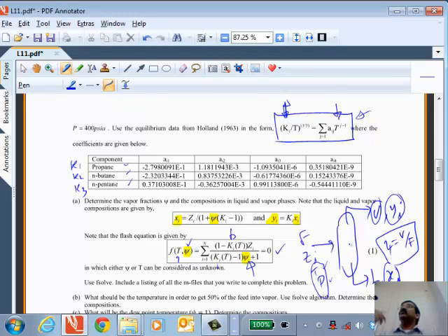So at dew point, what do you think will be the vapor fraction? Approaching 1, right? Because all of it is vapor, only one drop forms as a dew. Okay? So the vapor fraction is 1. So by putting vapor fraction equal to 1 in here, I'll be able to calculate the dew point. So the same formalism, same set of equations will allow me to calculate the bubble point temperature and the dew point temperature. Similar idea exists for pressures also, bubble point pressure and dew point pressure.